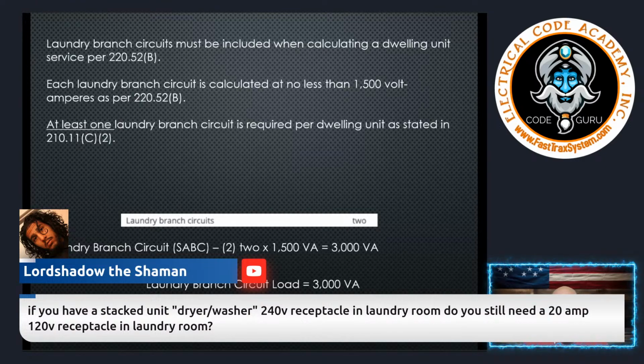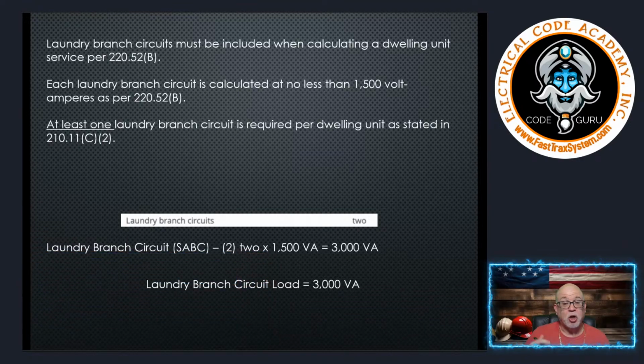There is nothing in the NEC that requires a 30 amp dryer circuit. Now, obviously, if you're on an exam and they give you a dryer, then you have to take that into consideration because they gave you the value. In fact, we do today on ours. But you're not required to put a dryer in, or to calculate for a dryer unless it's being used. And if it is, then you have to apply it.